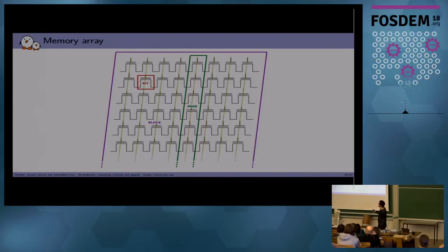And when you want to program this cell, by selecting this cell and applying a high voltage on this gate, you will actually select all the cells in that page. And that's why you can only program and read entire pages at a time with NAND flash.